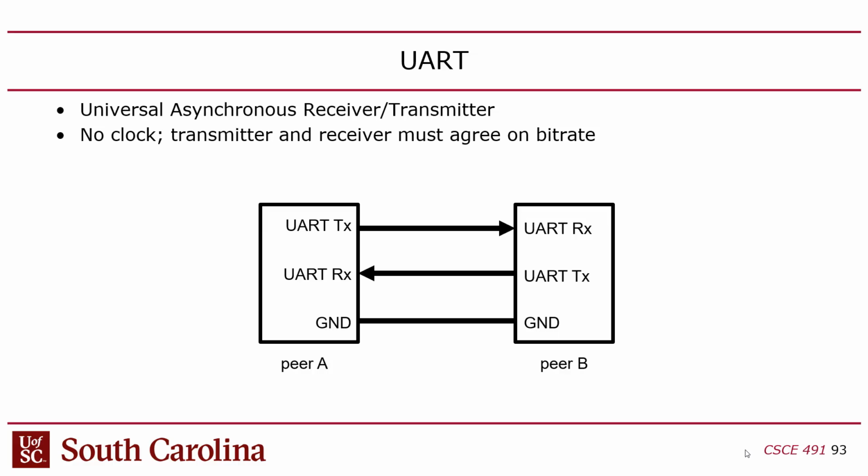You have a bigger ratio. So the probability of metastability goes down as you decrease the frequency, right? That's why you can't run UART fast, because if you run UART fast, it increases the likelihood of a simultaneous read and write because of the phases being aligned. The probability that the two clock phases are aligned is increased. Make sense?